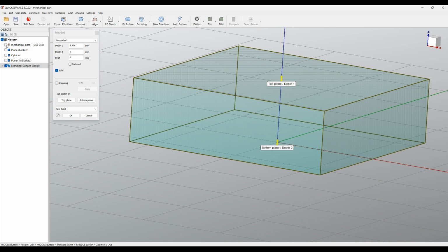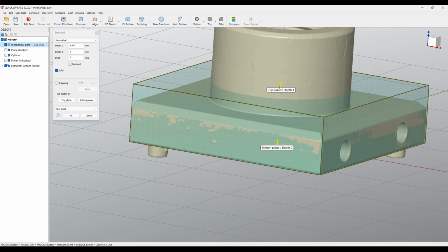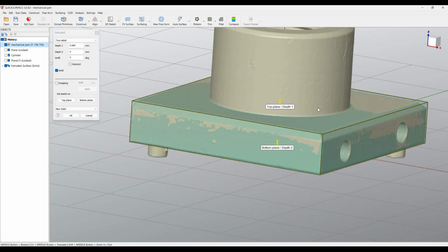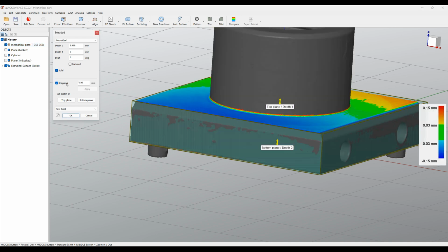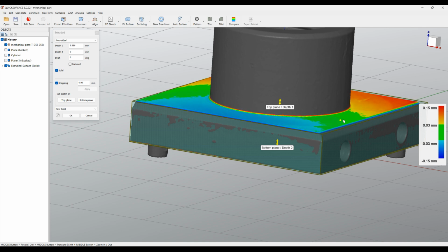Go and select the mesh so it's visible on the screen. I'm going to start dragging the top handle to a position onto the space, and we'll turn the snapping on so I can see where I can best fit. You can pick somewhere here. You can see the value is very weird, so you can adjust this to something very specific, 5.95 millimeters.